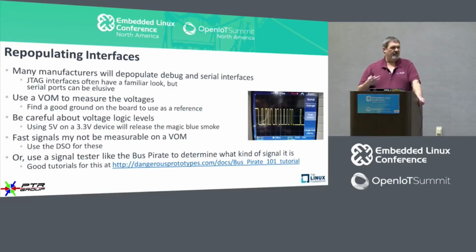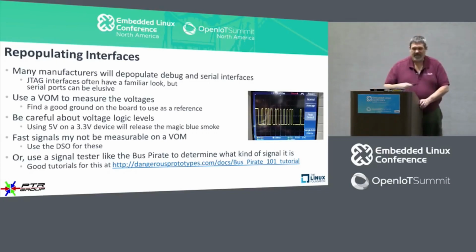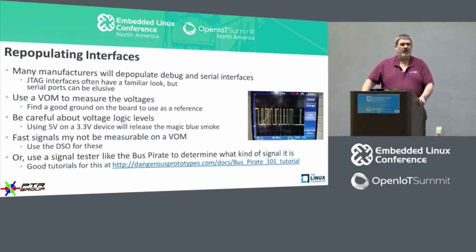Also, again, a caution here about the logic voltage levels. In this particular case, we put this scope on it. If you use a digital signal storage oscilloscope, we have high voltage probes that are available for that. So when you put that on the circuit and you're taking a look at it, you know you're not going to toast the scope. And the scope is made to be able to sample the voltage level, so we'll be able to see it.